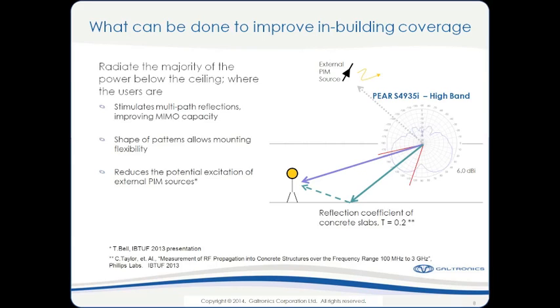So if I'm deploying a small cell DAS, I want to control where that power is, particularly for small cells where each small cell is an independent sector. So I need to be able to control my sector boundary and try to avoid these hard handoff scenarios when I get in gray areas between DAS and small cells, or when I'm outside, I don't want to be covering areas where I might be interfering with the existing macro network. So control of the radiation into a confined and defined space.